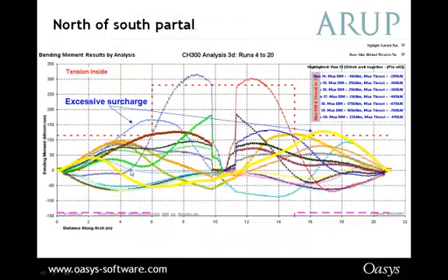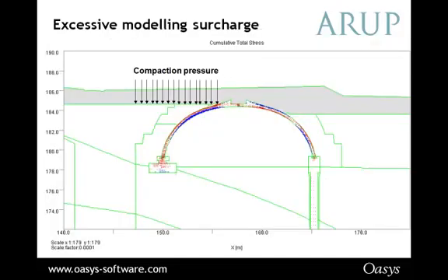And this enabled us to look at what bending moments are happening along the arch, what thrust forces are happening along the arch. So it's a very useful tool. And as you can see here, we've got the axisymmetric loading. So you can see that this compaction pressure here has made a big difference in the stresses, and something like SAFE and a finite element analysis program will bring out these kind of problems and really help you understand what's going on.